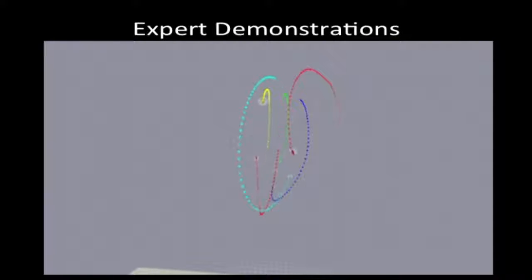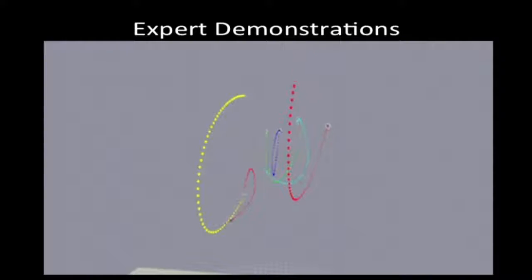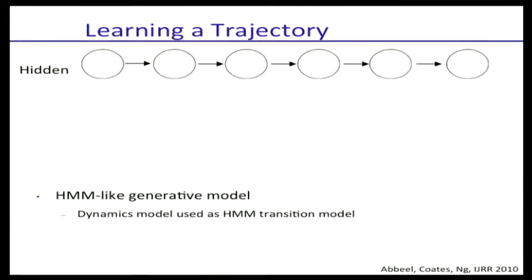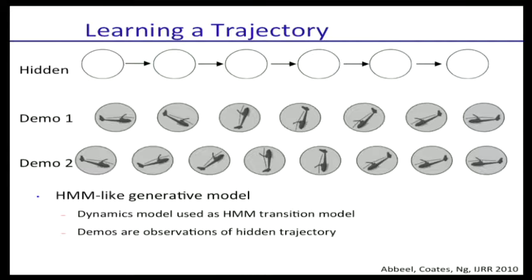And so by having just one track trajectory, you will get something pretty noisy just because of bad sensing and imperfect expert demonstrations. What we'd like to do is to take these many demonstrations and turn them into a target trajectory that's better than any one of them. One way to do this is to run inference. So you could set up a graphical model, much like a hidden Markov model, but in continuous state space. If you had 2 demonstrations, you could say, OK, now these are noisy observations of the actual demonstration I wanted. And let me run inference in this model.